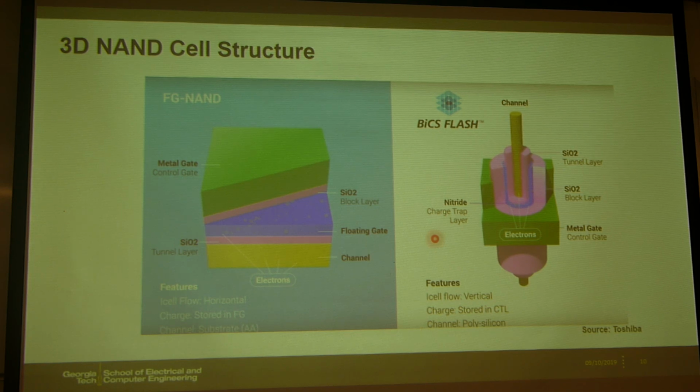Okay. So for 3D NAND, what's the dimension of your channel, like the radius? You mean gate length and? Yeah, just the channel diameter itself. Channel diameter is around 100 nanometer. Okay, so is everything deposited by ALD, like the gate? No. It cannot be because of time. Okay. And the gate length is around 30 to 40 nanometer.